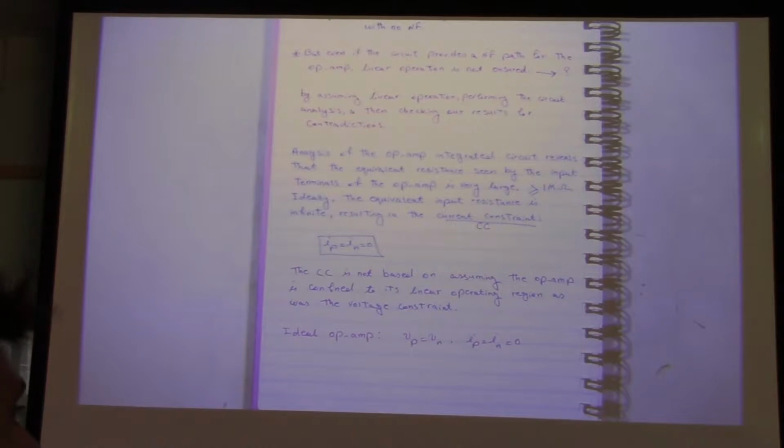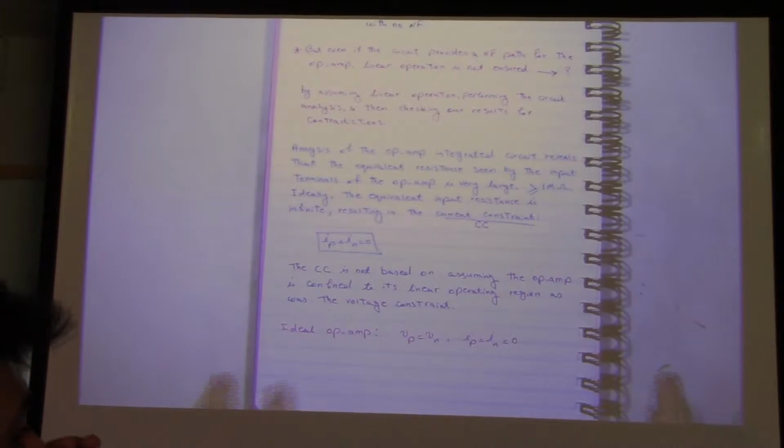But we are using large values at node voltages, usually 2 volts, which is 2,000 millivolts. So if one terminal is 2000 and another one is 2002, we can say they are about the same value. Clear? Questions? So, for an ideal op-amp, Vp equals Vn, Ip equals In equals 0.